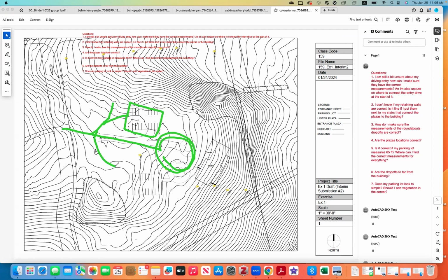This design, you could make it work, right? But I would say it does have more paved surfaces than the typical single loaded or double loaded design, okay? Because in order to not make both of these dead end parking, you need a drop-off area in both parking lots.